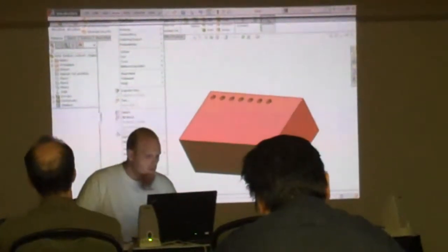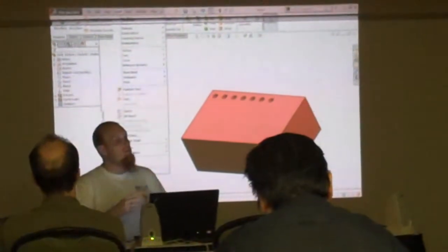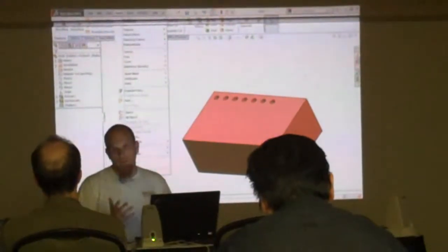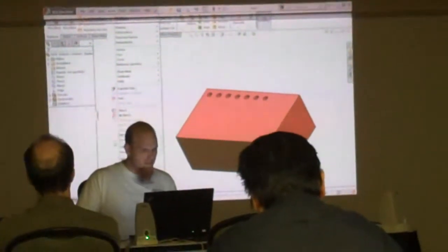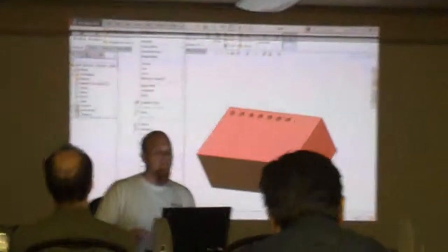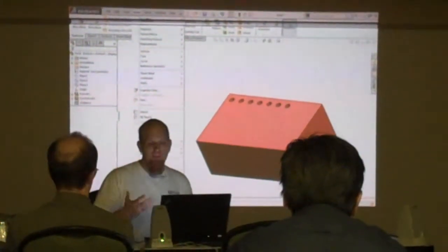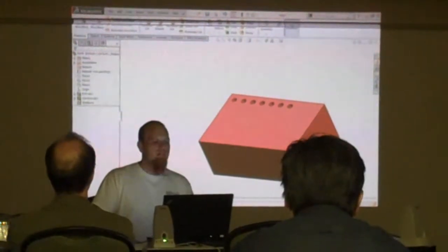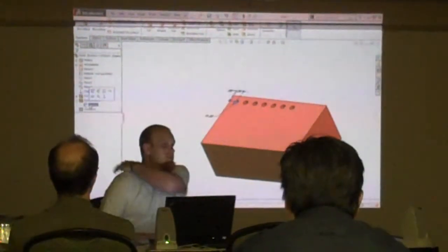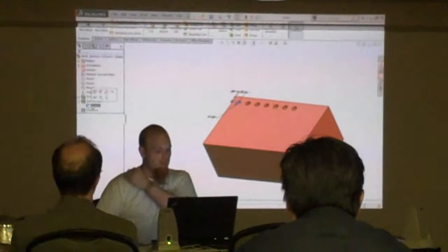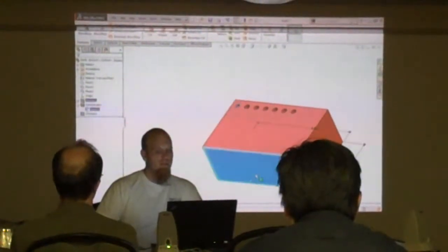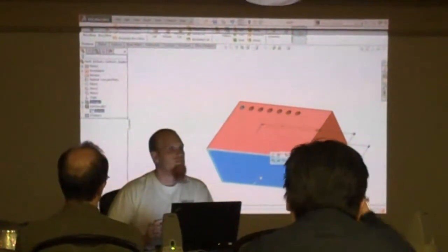It has no icon, so that you guys know if there's no icon, there's no button for it. So you don't need to look for it. All these are dead, they have no buttons. The only way to get it, and it's grayed out, and there's only one thing in SolidWorks you can do to get it from not being grayed out, and that is selecting the sketch that you want to derive, and control selecting the face you want it to derive to.